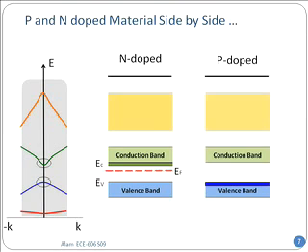If it is p-doped, that means Na, right? Lots of acceptors. Then I would have the Fermi level close to the valence band. And I have shown you deep blue, lots of holes, very few electrons. I haven't drawn that. I should, but I haven't drawn that.